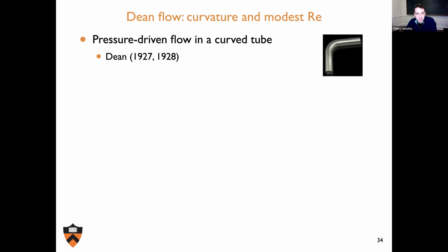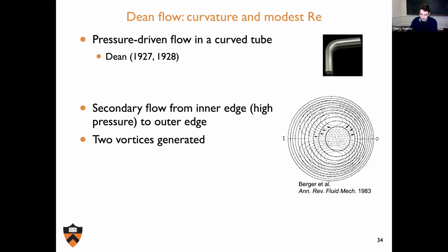Okay, so we wanted to understand this. There have been a lot of studies on flow in curved pipes or curved tubes. It's called Dean flow. And you see these centrifugal effects create these two vortices in this flow. I at the left denotes the inner wall, the inner curvature. O is the outer wall, the outer side of the curve. And you see the centrifugal effects just sort of fling the particles toward the outer wall and create these two vortices. So this is a very well-known phenomenon. And we observe similar effects in this T-junction flow.